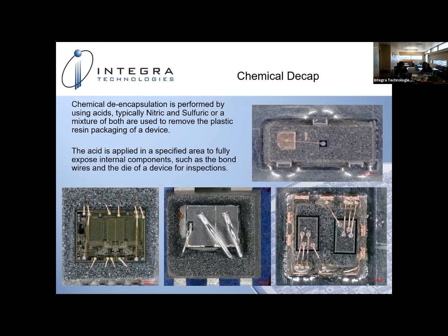And for the X-ray machines and the like, whatever we use in our lab, there are OSHA guidelines on how much dosage you can have in that lab for human safety. So we follow all of those OSHA guidelines. Yeah, through dosimetry. And this you may want to address a little bit later. Is destructive wire pull required on PEMs? You can do it in the PEM section. Yeah, it is. And I'll cover that too.